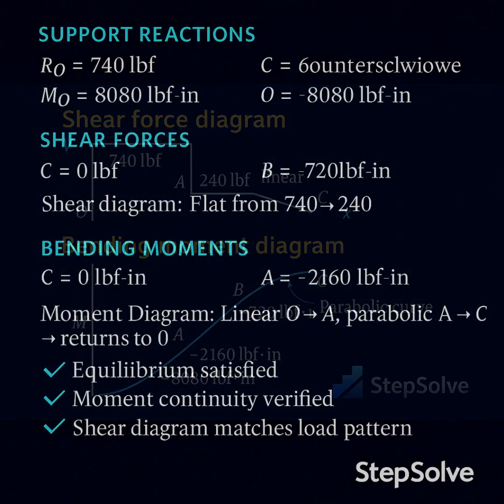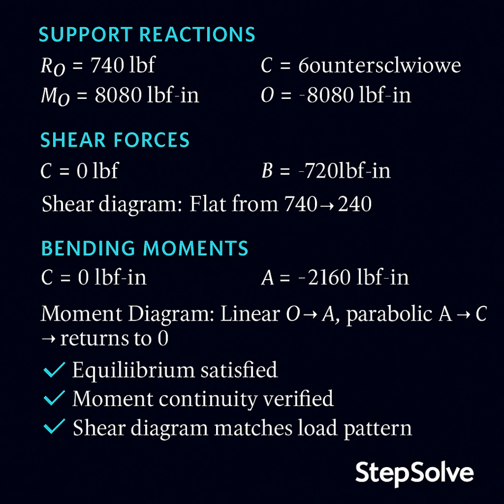All right, engineers, quick recap. Reaction at O equals 740 lbf up. Moment at O equals 8,080 lbf in counterclockwise. Shear and moment diagrams, done. Beam equilibrium, flawless.